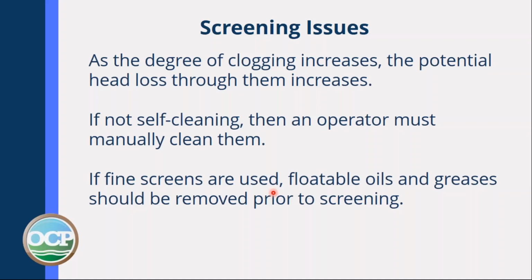So this is why screens are either automatically cleaned or manually cleaned on a regular basis, because as we saw in that slide with a higher level of water before the screen, you want to reduce that as much as you can. If you don't have a self-cleaning screening system, then the operator is going to get a little messy and dirty.